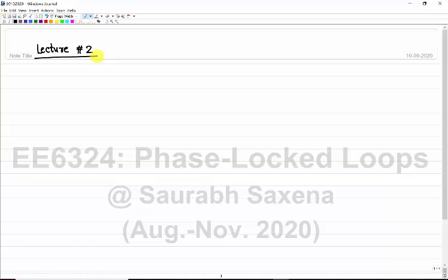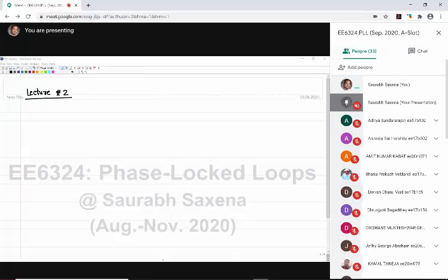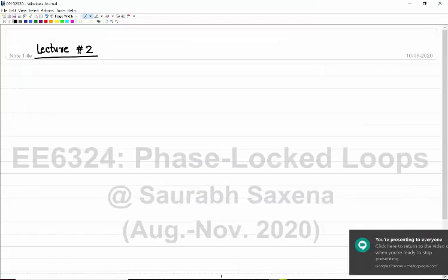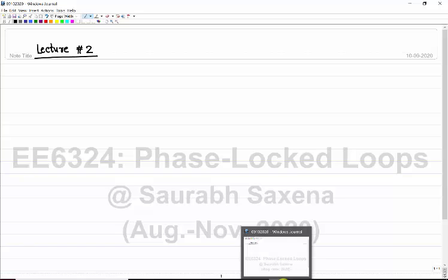Then we looked at the crystal oscillator, and we said that it can be modeled like an RLC circuit, but the frequency of the crystal oscillator is limited, so we cannot get whatever frequency we want. We need much higher frequency, and for that we can have different inductors and capacitors. But if we have a simple inductor and capacitor, you cannot have sustained oscillations, because there is a resistor associated with the inductor which will make the oscillations die down. So we have to come up with something which can keep this frequency of oscillation sustained.